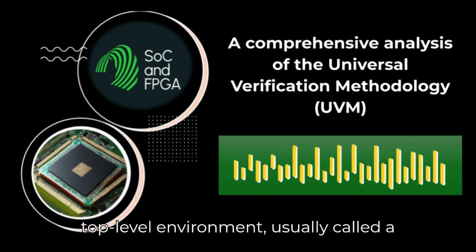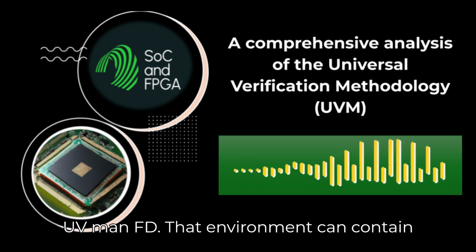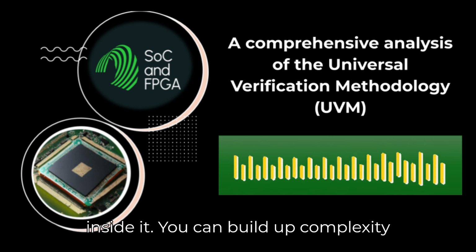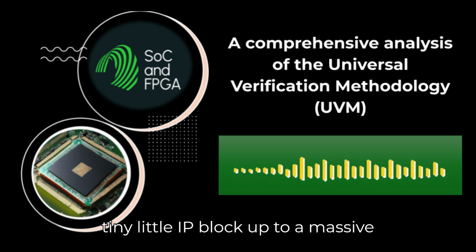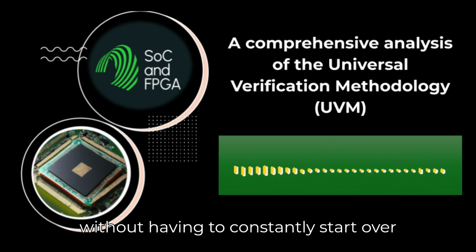You have a top-level environment, usually called a UVM env. That environment can contain multiple agents, maybe a scoreboard for checking, maybe other environments nested inside it. You can build up complexity seamlessly. This structure scales really well, letting you go from verifying a tiny little IP block up to a massive multi-billion transistor system on chip without having to constantly start over from scratch.